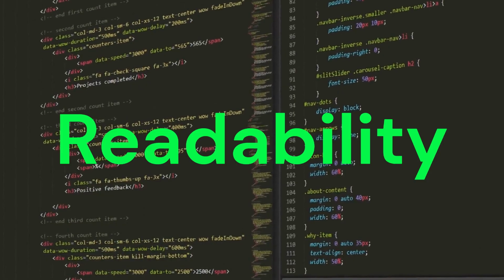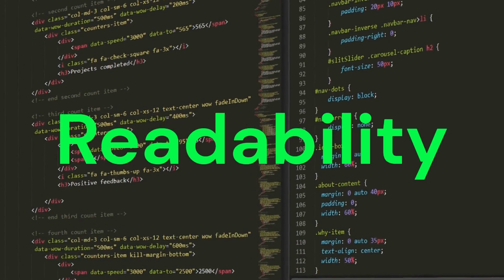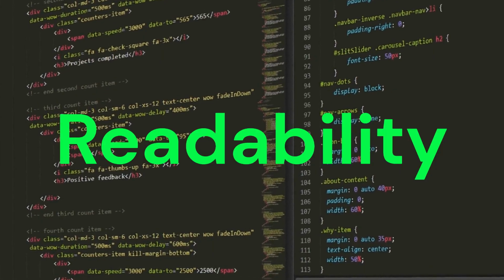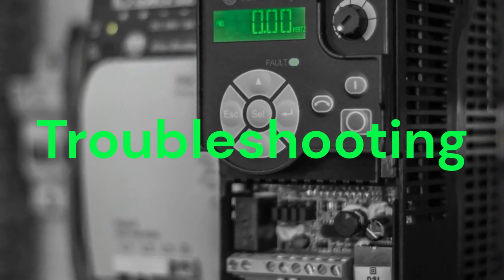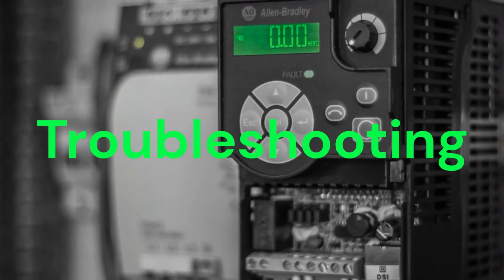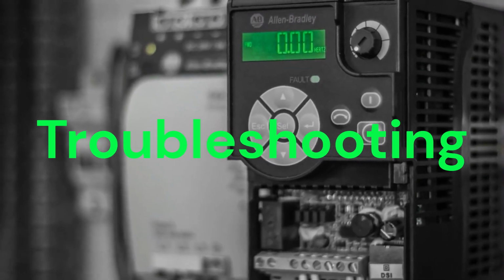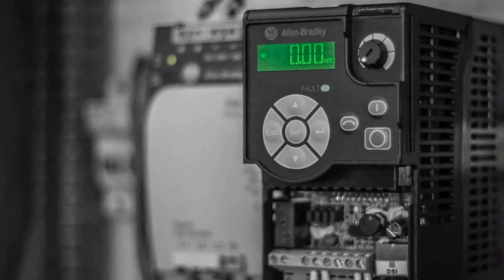Why do naming conventions matter? Readability. Clear names make the code easier to read and understand, not just for you, but for anyone else who might work on the system. Troubleshooting. When a machine is down, you need to find the problem fast. Descriptive names like motor status running are far more helpful than generic names like MTR1 stat R.